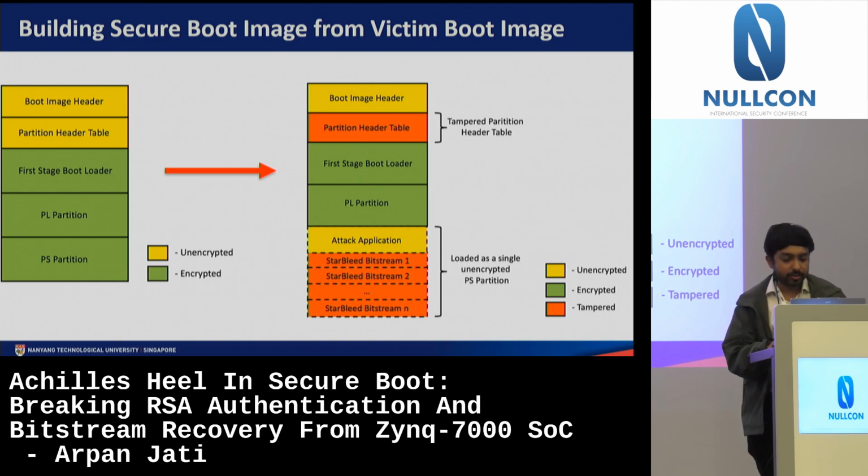I'll just go into some basics. On the left side we take a boot image header, and we manipulate the partition header table as I explained earlier, and then we can have lots of multiple bitstreams. We can have hundreds of them, and when the application runs, because the attack application is also in our control, it can run one bitstream after the other, and after running each one, it can send the data over UART so that you can copy and store it.